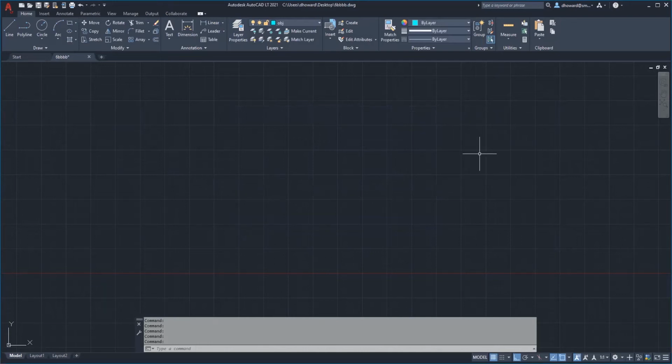I also talked to you about a new snap, this down here, one of these new tools down here on the status toolbar, the ortho mode. So leaving that on is a pretty good idea, and that limits you to drawing vertical and horizontal lines always. It's very seldom that you're going to draw an angled line. And if you're trying to draw an angled line and it won't let you, just turn that off. But I would just leave that on most of the time. And it's pretty handy.